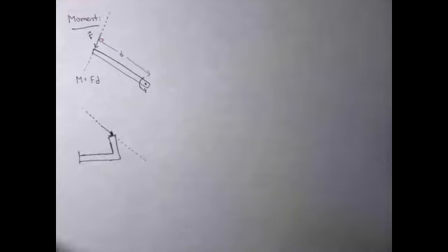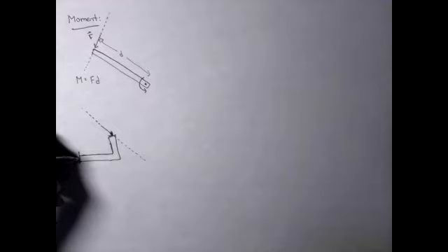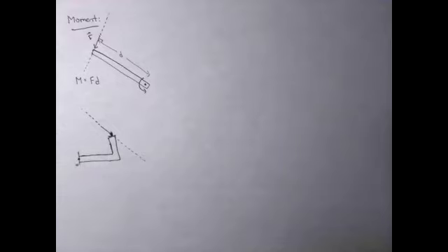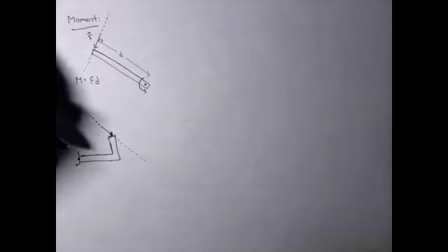And we said that if we wanted to find the moment about a point at the wall, in other words, at the other end of our object, then that distance d would be the distance that's perpendicular to the line of action. Now, sometimes that distance and the force intersect. Sometimes the distance will touch the line of action, not necessarily the force vector.